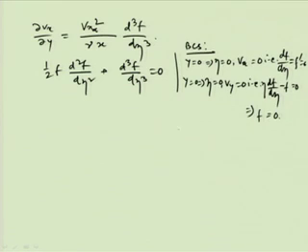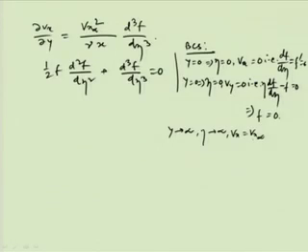And then at y tends to infinity, eta tends to infinity, and then Vx is equal to Vx infinity. So, here we can understand y tends to infinity means y is close to the boundary layer thickness, then Vx is becoming Vx infinity, and that is df by d eta is equal to f dash is equal to 1.